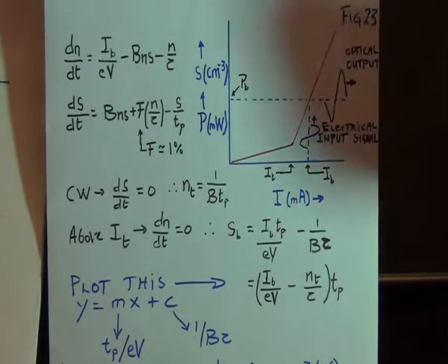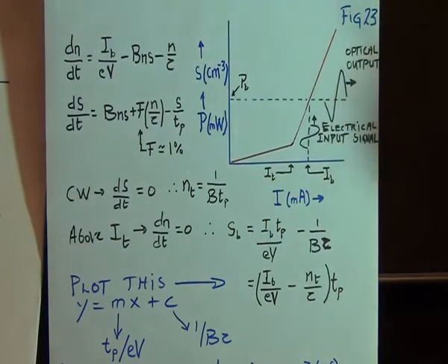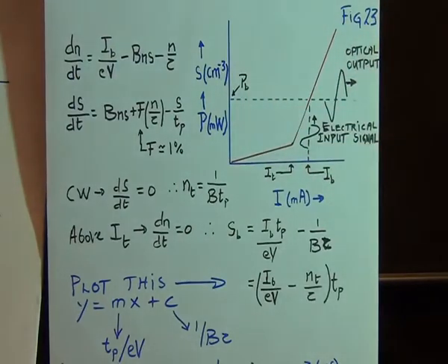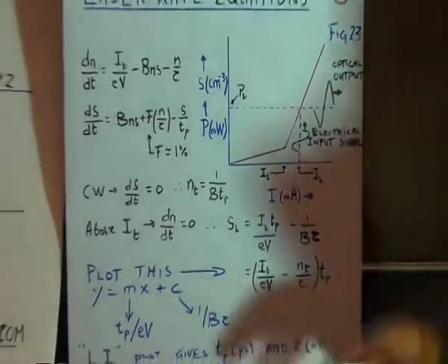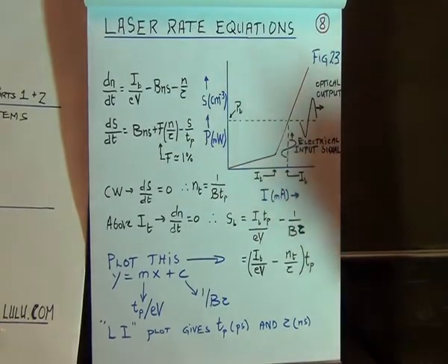They're very important because those parameters turn up all over the place as you play around with different aspects of the lasers. You'll find the photons live for a couple of picoseconds before they're emitted. The carriers live for a couple of nanoseconds, 1,000 times longer.